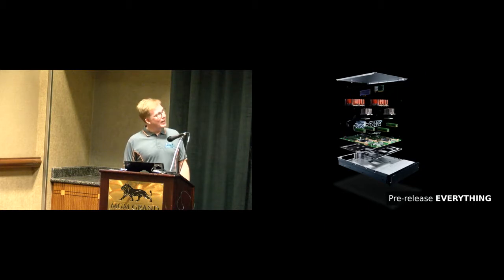There can of course be bugs in the memory controller talking to the RAM, but we can definitely mostly count on them to work. The fans, believe it or not, we have revisions in fan assemblies and how we interact with them from the BMC. And of course, if you can't pump enough air out of it, you're not cooling things as much, so you're not going to get higher CPU frequencies. So a performance problem on the host that you think could be a firmware problem of, oh, you're not setting the CPU frequency, could actually be because the BMC isn't controlling the fans correctly. So we've had revisions in fans.